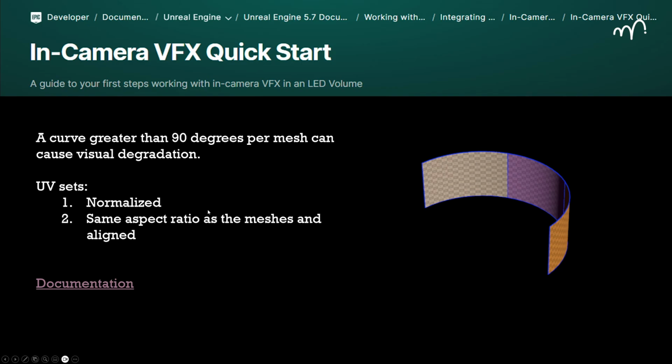The other important part is it needs two specific UV sets. One is a normalized UV set, so for each mesh that we're going to be generating, we're going to need the 0 to 1 normalized UV coordinate space. And then the second UV set is going to be the full mesh aspect ratio, basically. The scale doesn't have to be normalized into the 0 to 1, but you keep the aspect ratio so the actual projection will be even for your texture patterns and stuff like that.